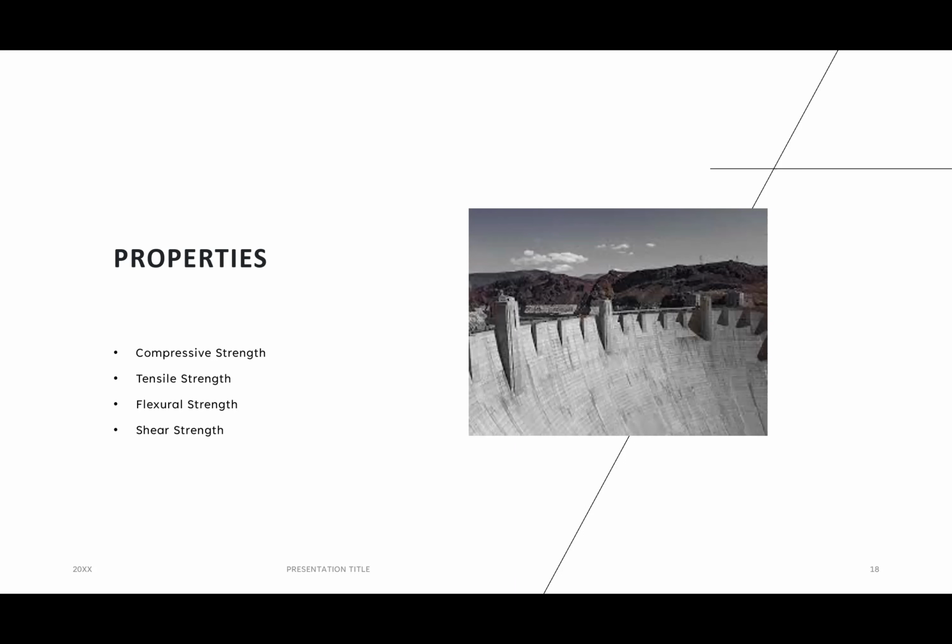Then the tensile strength. The tensile strength of concrete is also a very important parameter that is considered in the design. It can make a significant impact on other strengths of the structural element, and in flexure, as it is about 10% of concrete compressive strength. A concrete element can be subjected to pure tension or a combined effect of compression and tension.